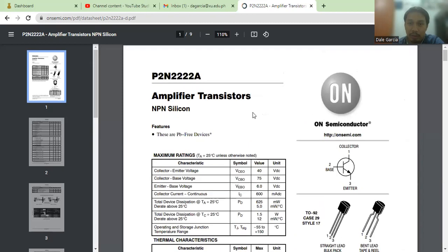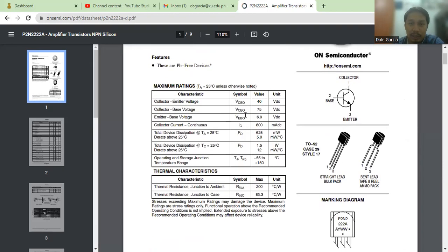What is significant in solving for IC and VCE is that it's for checking against the specification sheets, whether it's still far from the limit. And this is the limit, 625. So that's still far. It's 16 only. So still far.